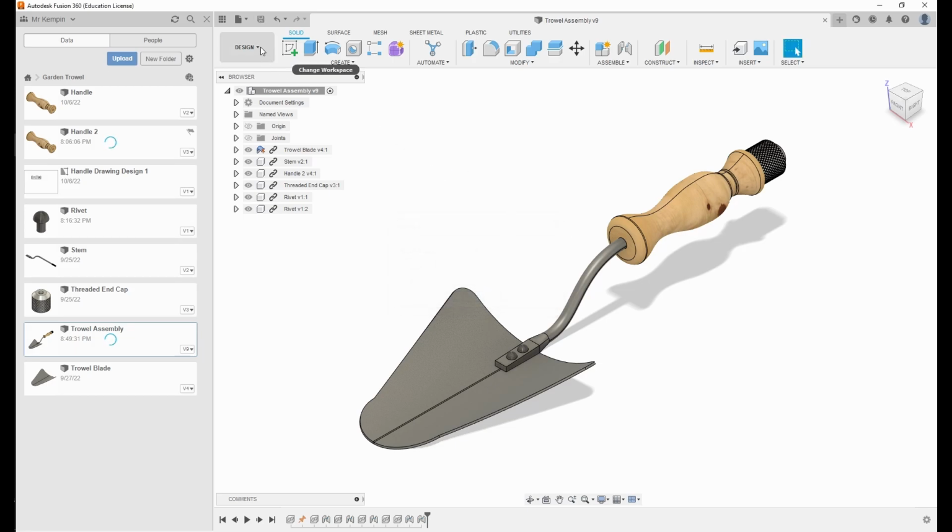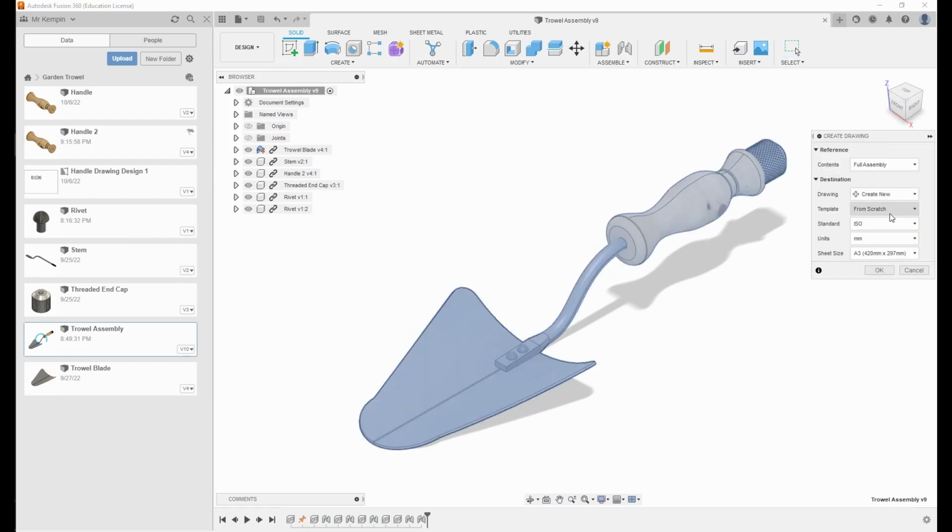And once it's saved, we can now go to design, drawing from design, and template. We can choose from our list of templates here. So Trowel Smart template, that's the one we just made. Click on that. You can see here that my units can't be changed. That's as I want them. External components, yes, for this scenario, I want them.